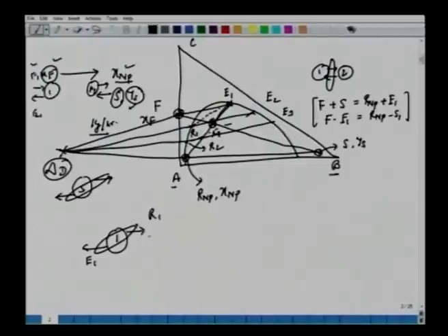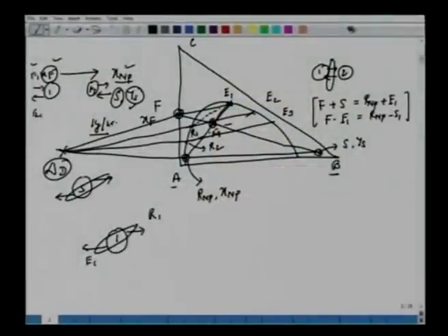The idea here is very similar to what we had in the case of a distillation column. We located delta D and delta W points because the difference between the molar flow rates of the two streams arriving and leaving is a constant, equal to the top product molar flow rate or the bottom product molar flow rate. We have a similar approach here, realizing that the difference between the raffinate and extract, at stage 1 or stage 2 or stage S, anywhere, is a constant difference, so we locate these difference points. And once we know the difference points, we can have the operating line and the tie lines, and we can proceed.